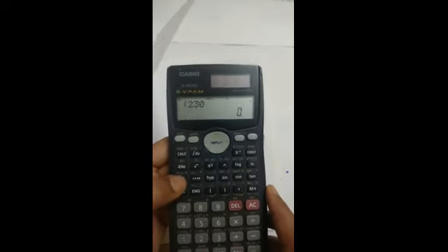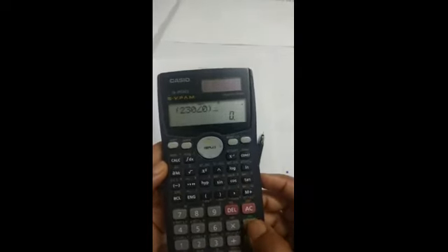In brackets, the numerator should be 230 at an angle (use the shift button here, then enter) 0, divided by. Again take a bracket, because this is completely complex form. Then you enter 20 plus j31.4. We do not have j on the calculator, so we use i. Close the bracket and enter. You get the rectangular form,